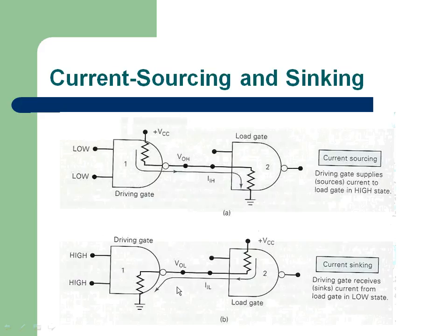In the other case, these two are high and these are low. So in this case, what happens? The output is low. In the sense, if it is a TTL logic family, the transistor is in saturation. Then through the transistor, through that collector-emitter saturation junction, this current has to sink. So the maximum current handling capability of the transistor will become a limiting factor in this case. So for the fan out, this could be limiting, this could be limiting. Whichever is minimum, we have to consider that.